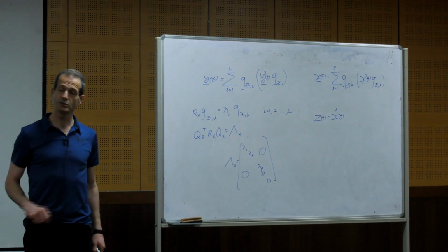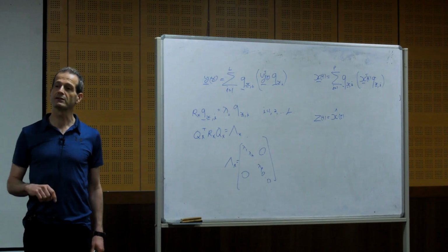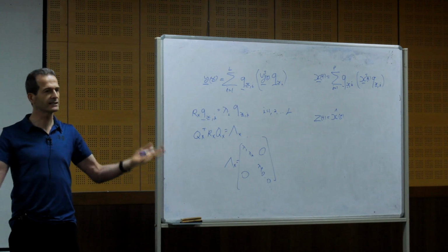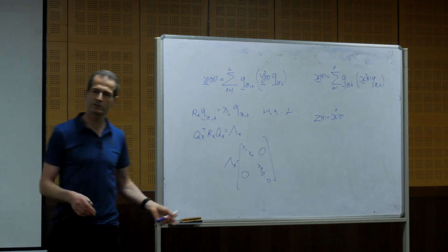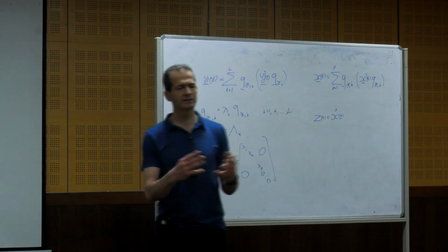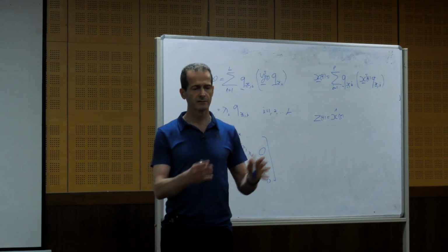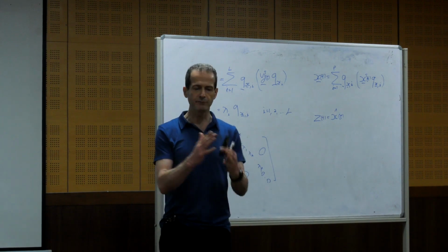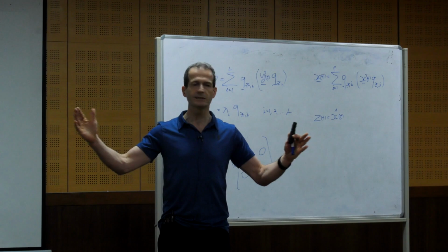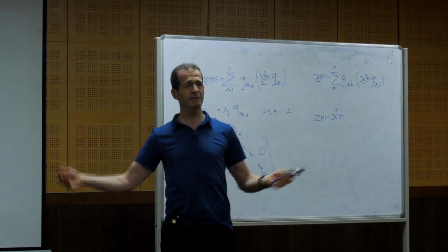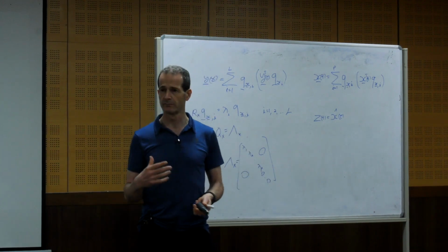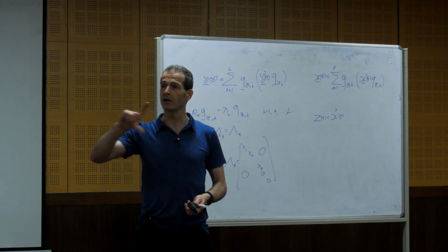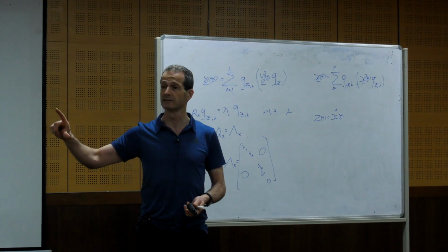But I will give you also some interesting thought. When we talk about the signal, maybe the signal is stationary or not. But if the signal is not stationary, suppose, for example, a speech signal, if you take the Fourier transform of a long speech signal, it can be a few seconds of speech, you will identify that the signal is present in all frequencies.